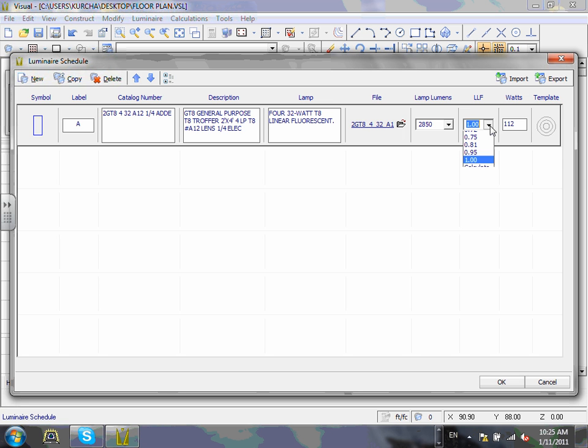Remember when I was talking about the light loss factor, a combination of all these factors in your building. If I remember right, for fluorescent indoor, at least, and you can change this at any time. Don't touch it. They usually default it to 81. That's what Davis and Associates told us. They might change their mind this time, and I might have forgotten it. So default to 81. If you didn't change this one now, you can change it anytime with your calculation. So remember, guys, the depreciation factor, luminant, and all this stuff.